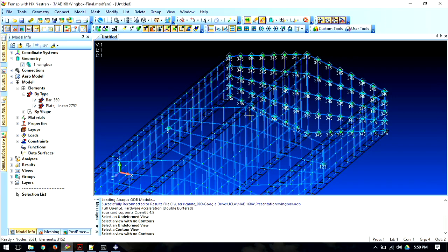And then here's my wing to fuselage constraints. So here I pinned it, 1, 2, 3, so it's not allowed to move. It can rotate. That's why over here I simply applied a vertical constraint. That way it's fully constrained. So this would be some kind of pin joint on my spar, and it would mate to the fuselage there. And over here it'd be some kind of a lug.